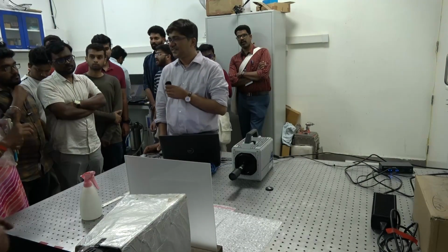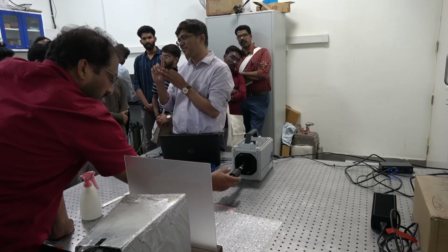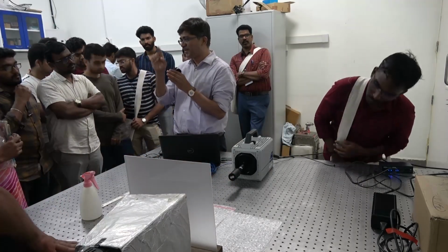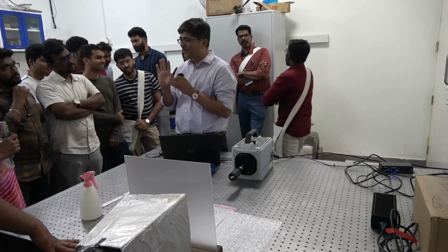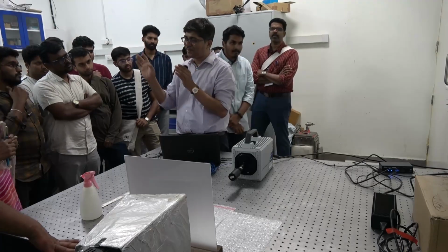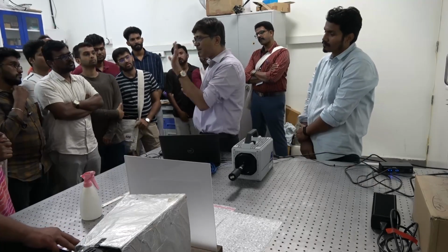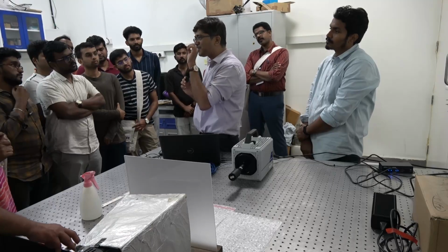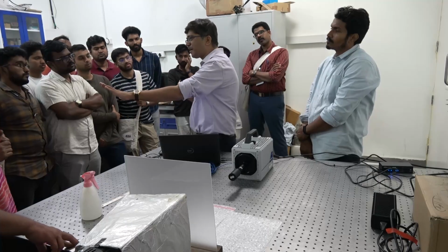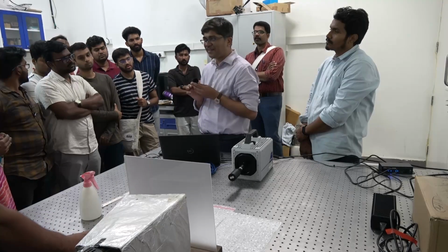Is that one reading enough? No, different size drops will have different velocities. So you need to process and get the velocity for this drop size. This is the velocity. If you want, you can take an average velocity, and again this is the size of the drops, then they will have an average velocity. And in the morning, as I was telling, in a spray with different size drops, the smaller size ones lose momentum very quickly. Their velocity will reduce, suddenly they'll stop, and the larger size ones travel a bit more. So you will not have a single velocity.